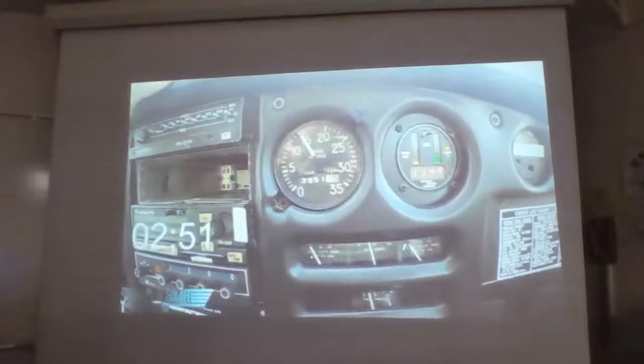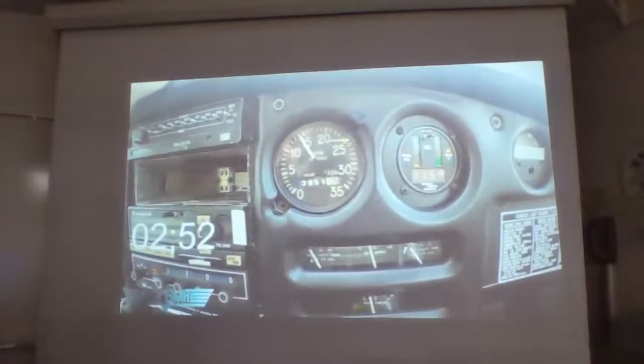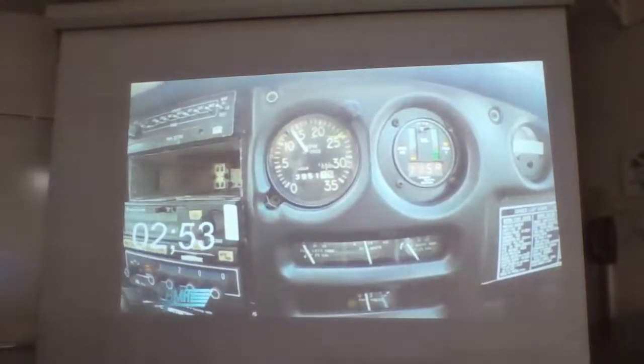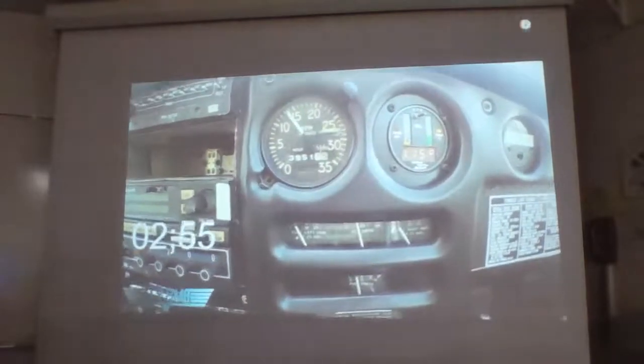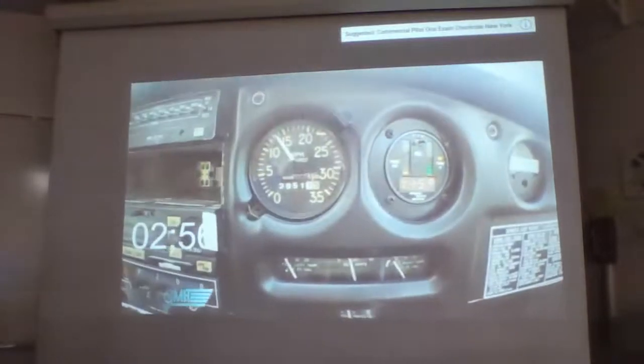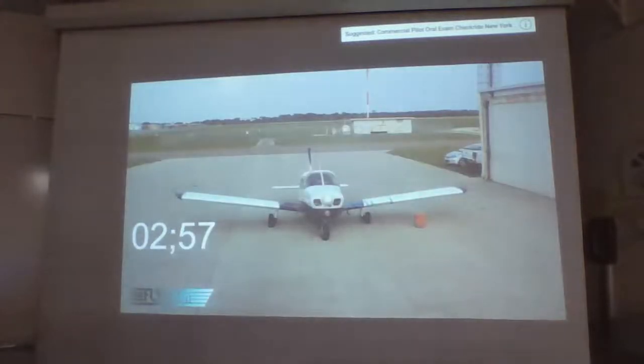Something's happened because we've lost a lot of RPM, so we might have possibly stuck a valve at this point. May not have even really started to seize the engine, but we might have stuck a valve or something. The vibration's not quite as noticeable as I'd expect with a stuck valve. We'll talk more about sticking a valve here in a sec, what that might mean for us.